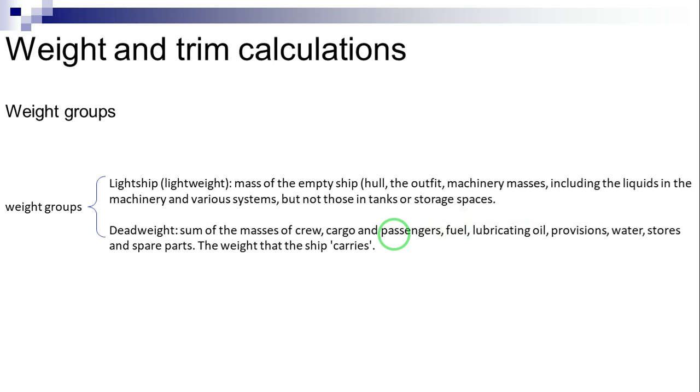In the first stages of ship design, known as preliminary design, the light ship masses and their centers of gravity are estimated by empirical equations based on statistics of similar ships, or are derived from the masses of a given parent ship. For merchant ships, the light ship groups are the hull, the outfit, and the machinery.